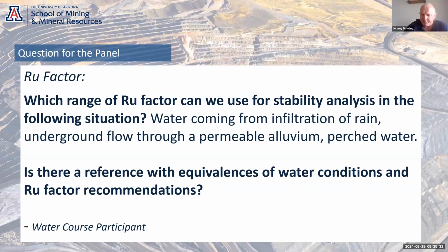Yeah, I've seen it used to best effect using a sensitivity-based approach. Especially in very shallow transient parts of the pit slope in the excavation damage zone, for example, the amount of water that's present can be extremely variable because of the distribution of fractures and where the local recharge sources are, and the seasonal nature of recharge and so on.